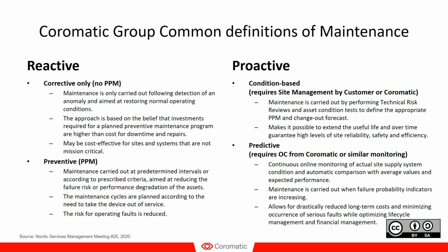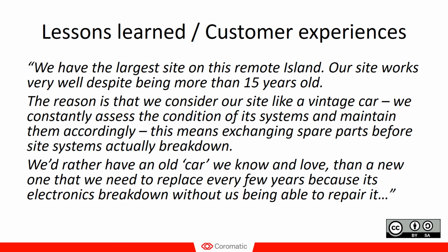Some lessons learned here: this is a site owner that has the largest site on a remote island, and their site works fantastically well even though it's more than 15 years old. What they've done here is that they handle their site as if it's a vintage car or a classic car. They work very much with condition-based maintenance and replace the components and exchange spare parts before the systems break down.